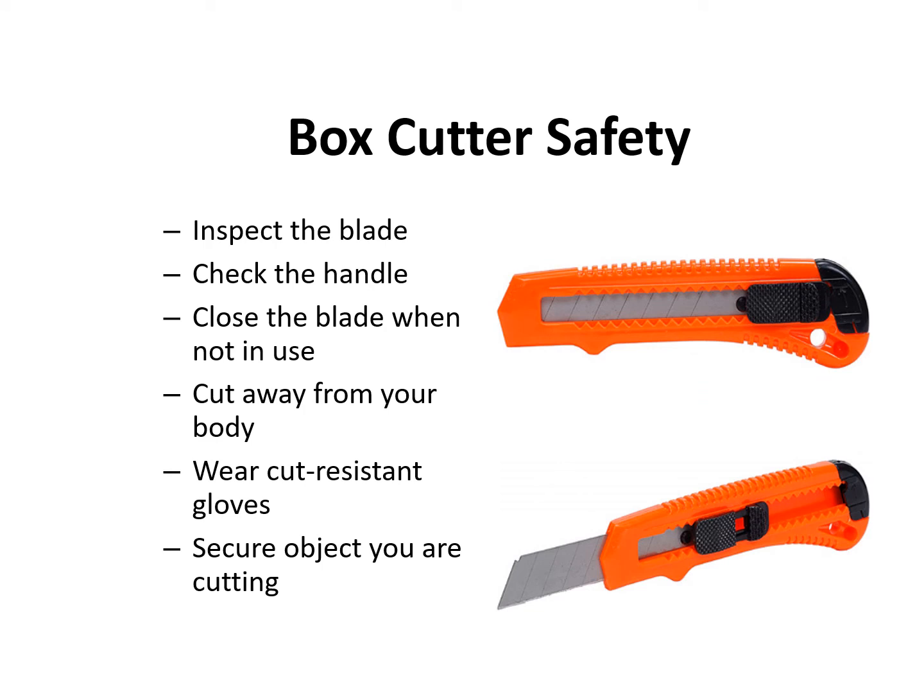When using a box cutter, inspect the blade to make sure it is sharp. Replace the blade if necessary. Check the handle to make sure it is firmly attached to the blade and there are no signs of damage. Close the blade whenever the knife is not being used and always cut away from your body.